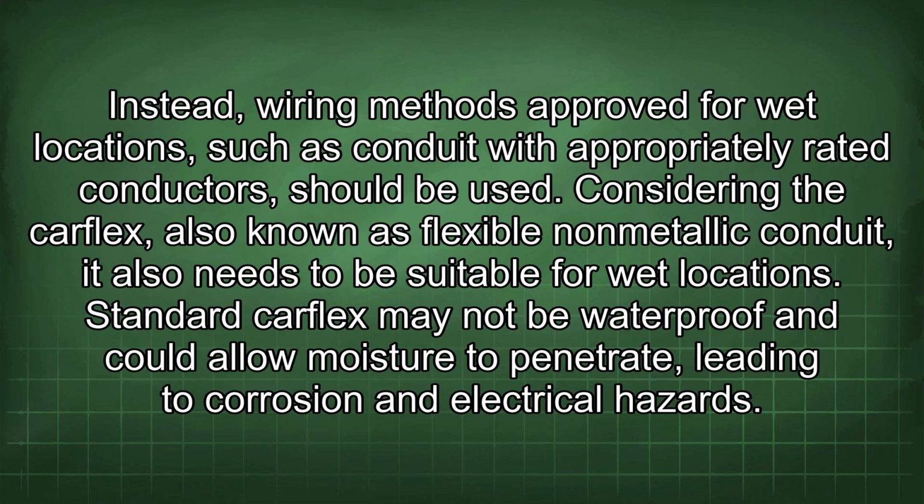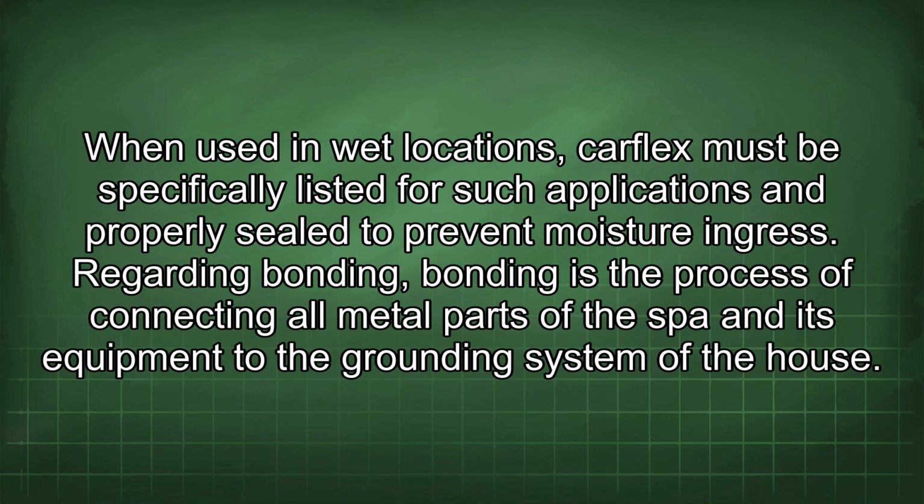Considering the Carflex, also known as flexible non-metallic conduit, it also needs to be suitable for wet locations. Standard Carflex may not be waterproof and could allow moisture to penetrate, leading to corrosion and electrical hazards. When used in wet locations, Carflex must be specifically listed for such applications and properly sealed to prevent moisture ingress.